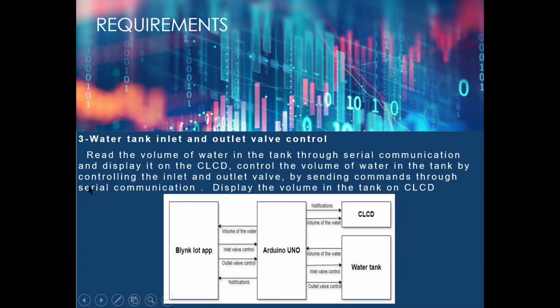Water tank and inlet outlet valve control. Read the volume of the water in the tank through the serial communication and display it on the CLCD. Control the volume of water in the tank by controlling the inlet and the outlet valve by sending commands through the serial communication. Display the volume of the tank on the CLCD.